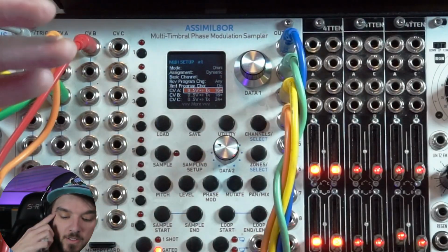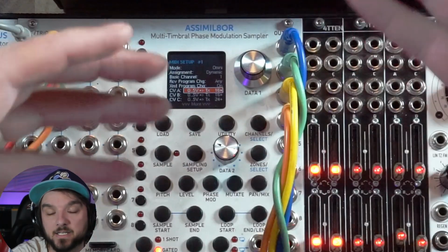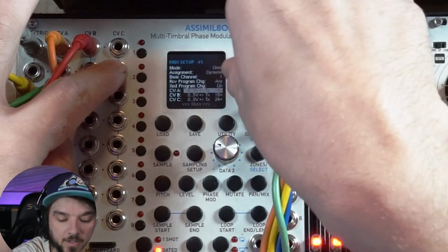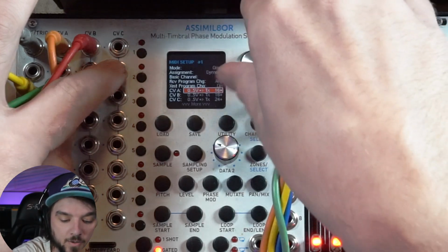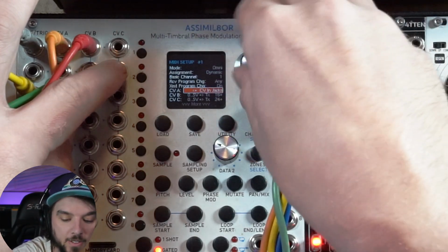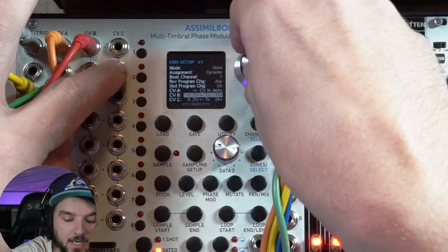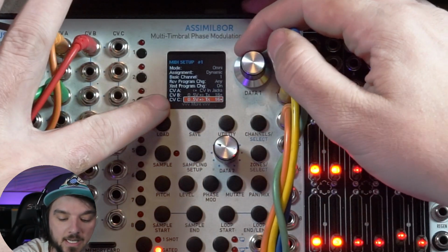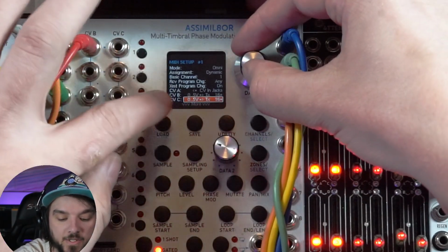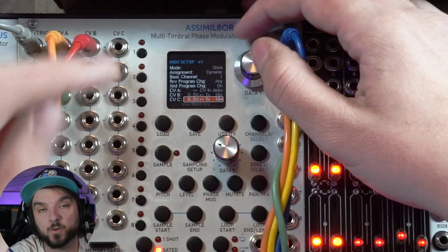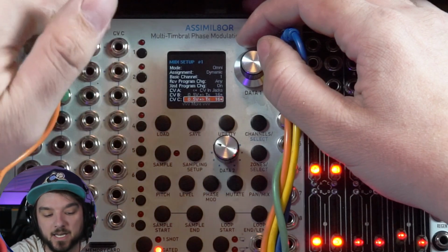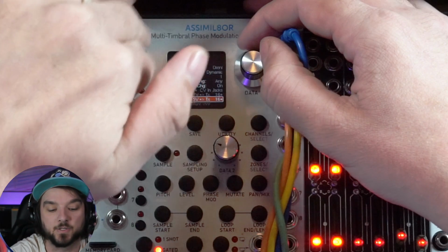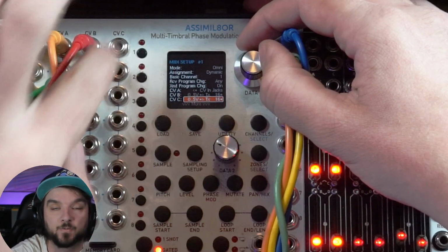And so now to figure out what CC you are transmitting, it's pretty easy. I'm going to go down to C because we don't want to use CVA for this. We want to use CVC. And we're going to see right here, you can see TX, that means transmit, right? It says 16 plus. So that means that we're going to go CC 16 and then up 8. So 16, 17, 18, and so on are our MIDI CC numbers for the CVs.